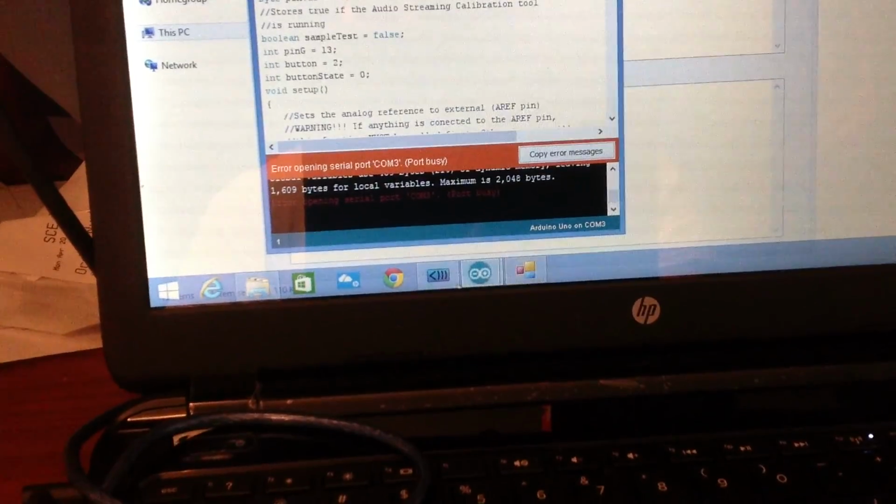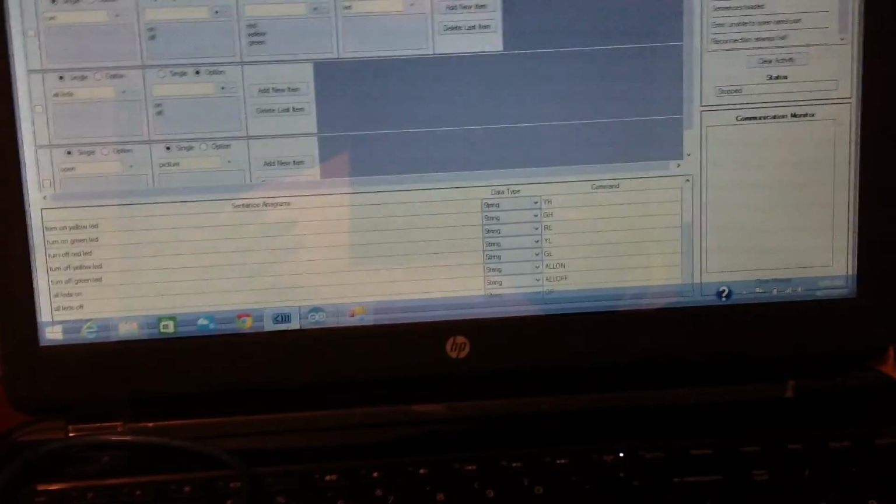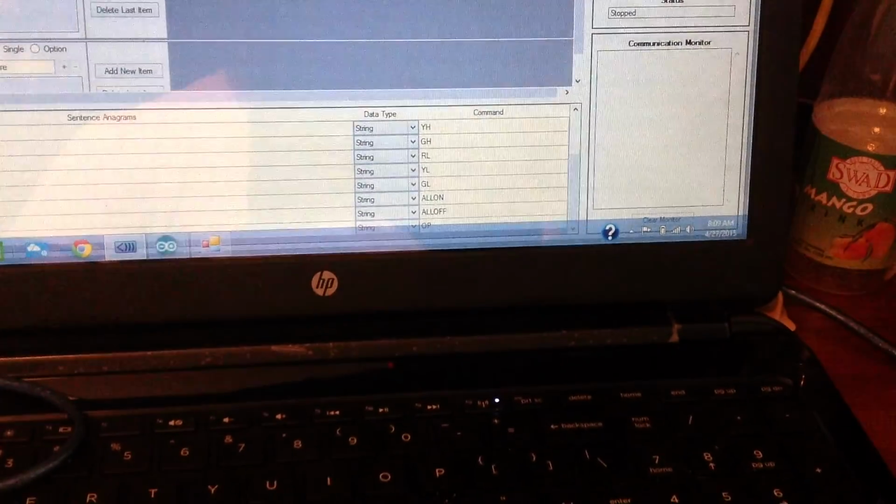So Bitvoicer, where to go? Right here. Bitvoicer is going to kind of block it, lock it, so then no other program can use that serial port. And GoBetweeno needs to use that serial port. So does Bitvoicer, so does Arduino. So because of this, GoBetweeno won't be able to actually execute that command.